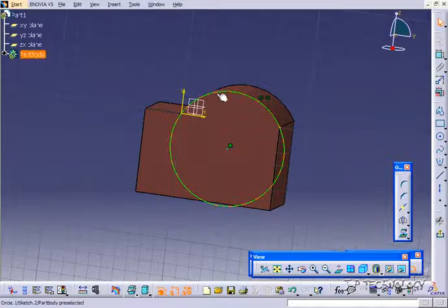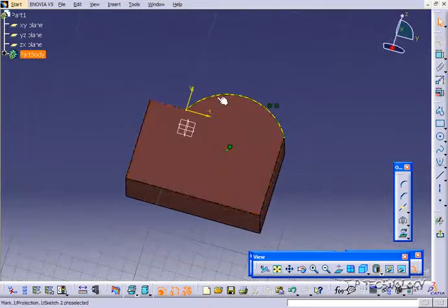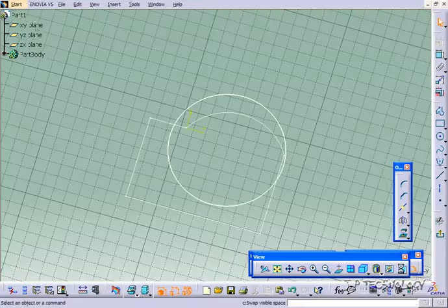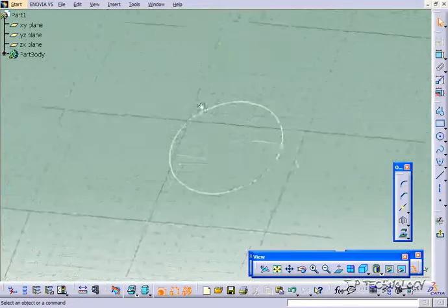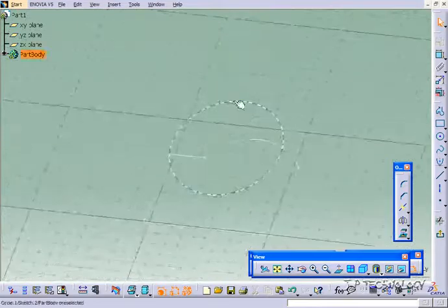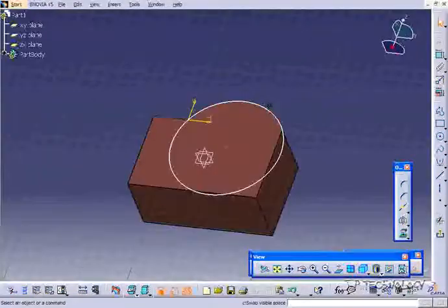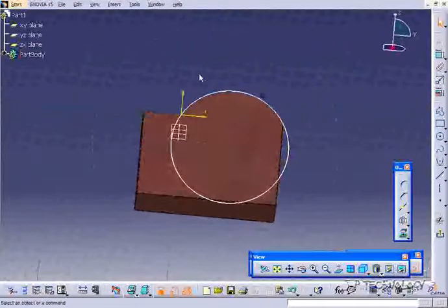So to do this, what we're going to have to do is right-click on this sketch that we just made, click Hide, and now we're able to see that sketch behind it that we need to delete. If we didn't hide it, there'd be no way of selecting that edge and deleting it. So let's click and click Delete. Now we'll swap our visible space, and when we swap, we're able to see the drawing that we just hid. So let's right-click on it, click Show, swap again, and now we have our drawing.